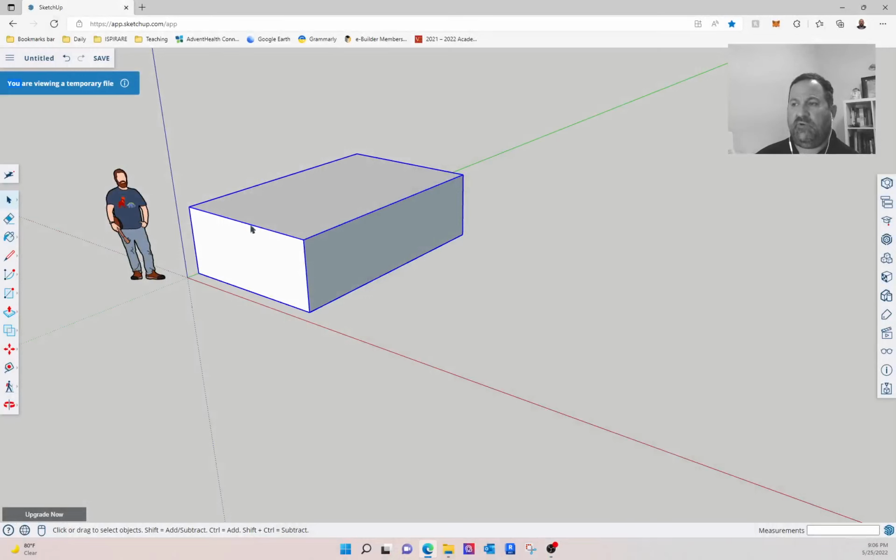So to start out, I want to show you again the same component we made last time, but this time I'm going to choose the move tool, right? And using one of the object snaps. Now, SketchUp's really brilliant in this way because it tells you what you're snapping to. In this case, I'm snapping to the bottom corner, origin in blank mass, which is what I named this component. Corner, corner, corner. You can also choose the midpoint of that surface. You can choose the midpoint of this surface. You can choose that corner. So any of the snaps will really be a benefit. But for our purposes, I'm just going to choose the back corner.